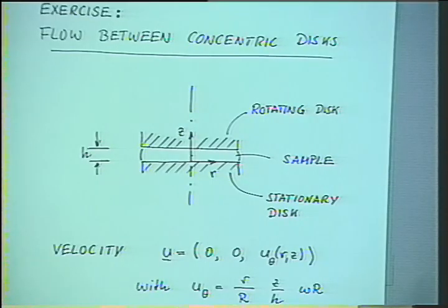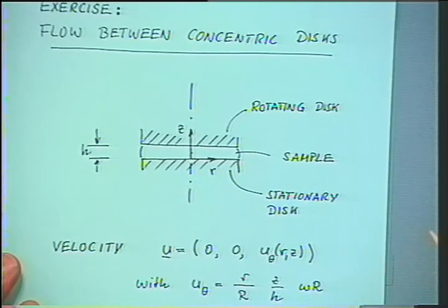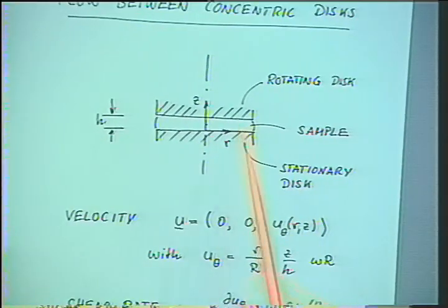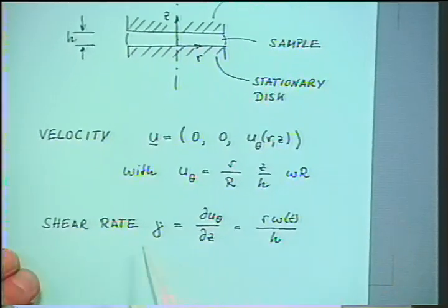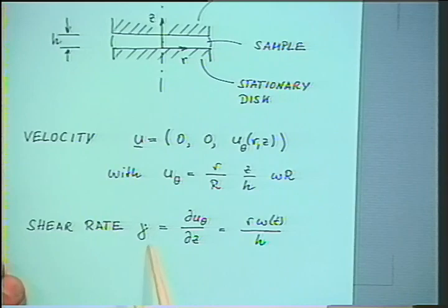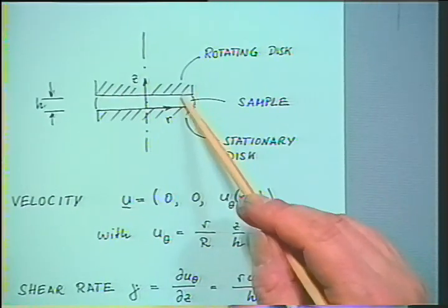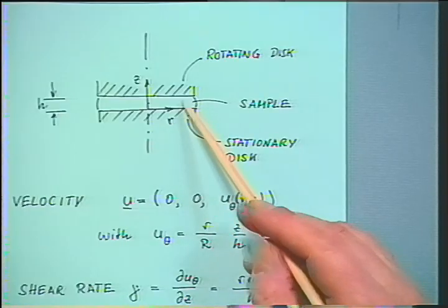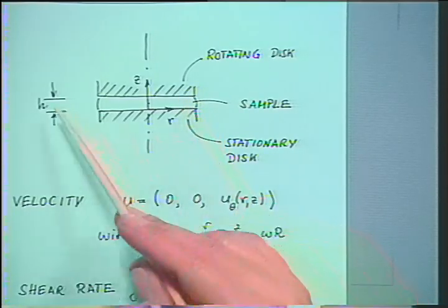If we have some secondary flow, if the experiment goes wrong, they might move all over. But we desire, for a well-defined experiment, we would like to have circular streamlines for our material particles. The shear rate in this case is given by the relative motion between the top and the bottom plate, and that motion divided by the spacing, h.